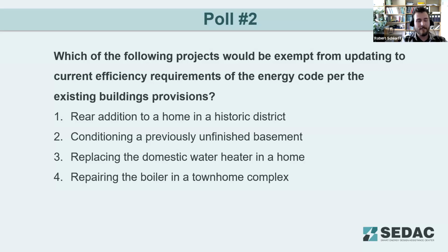Depending on the extent of the fire, if the fire covers potentially more than half of the building, you may have some other requirements there, but you'd have to talk with your local code official. And if you're altering the assemblies that you're putting back, if you're not replacing the fire damaged assemblies with the exact same assembly, you might also potentially trigger something. Do I have that right there, Sean? Yeah. To the best of my understanding.